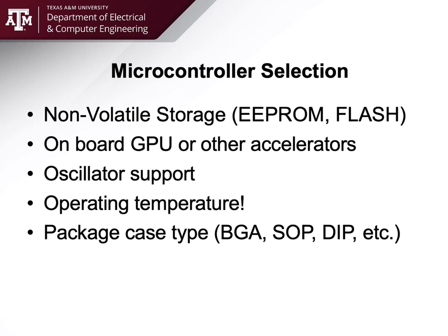Package and case. Small outline package, perfectly fine. Dual inline package, this is through hole, perfectly fine. TQFPs, perfectly fine. QFNs, difficult but fine. Do not, do not, do not choose a BGA. Someone will. It historically happens because sometimes it's the first thing that pops up. I got a really, really great microcontroller. It does everything I want.